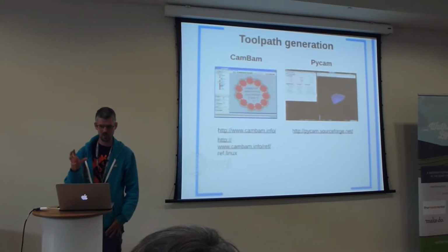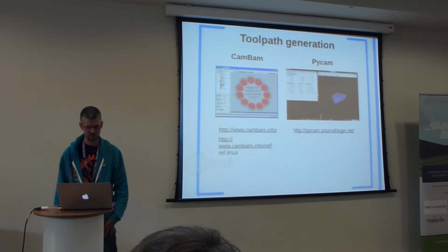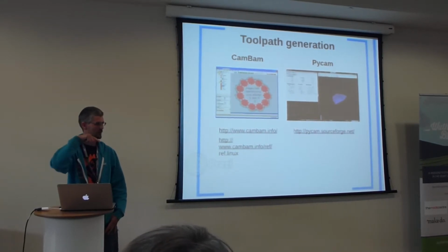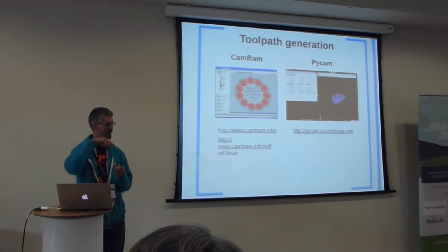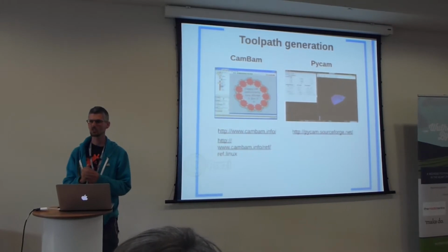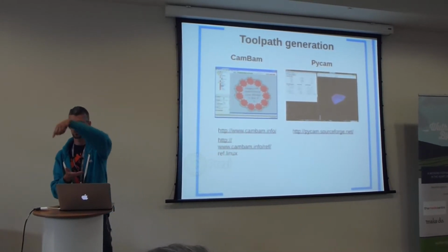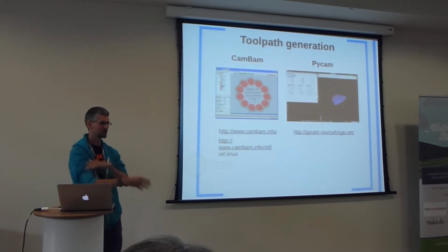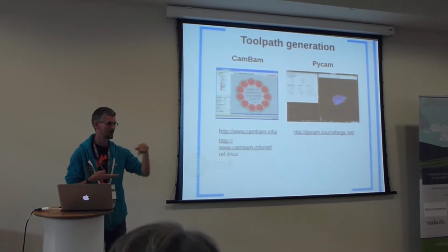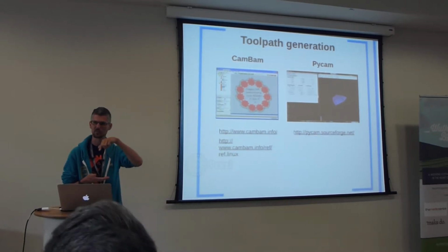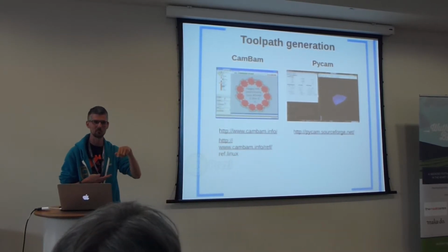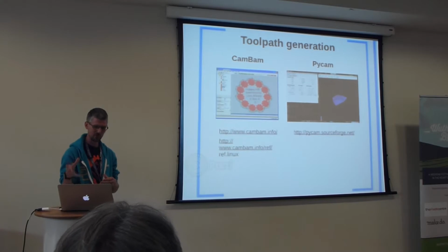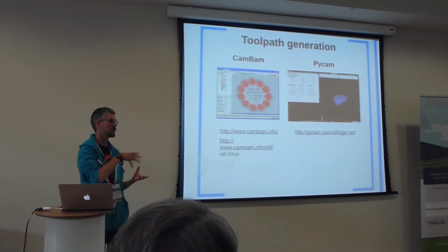And then a really important part is toolpath generation. So you've got your outlines, but now you need to turn that into what a machine can do. Usually with a laser cutter, you're just doing one outline and that's the end. But if you're cutting, say, 5mm aluminium on a smaller desktop machine like mine, I'll do that in maybe 10 passes, cutting out 1/2 mm each time. So I need to have a program that works on my vector files and then turns that into a toolpath.